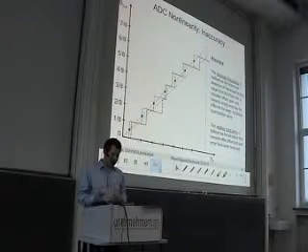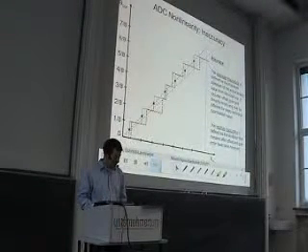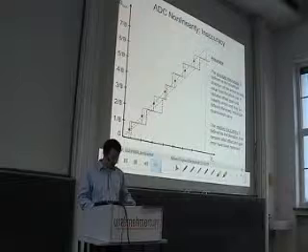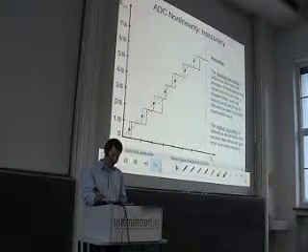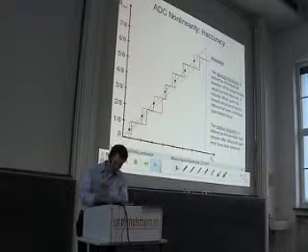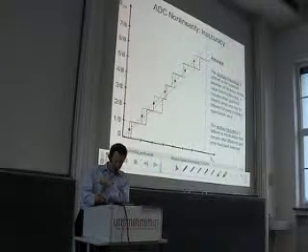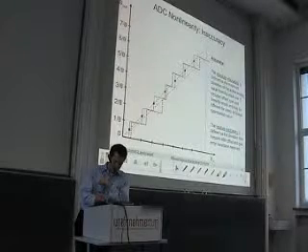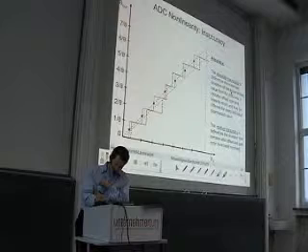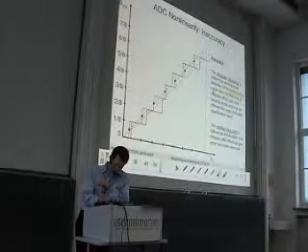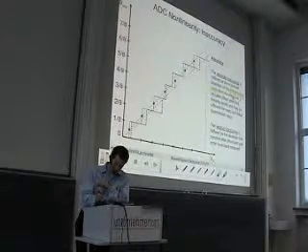However, I again give you some pictures that explain how you should interpret these definitions. Okay, let's read it again. The absolute inaccuracy is defined as the deviation of the actual analog value, so it is important that we always refer to the analog value, from the ideal one.